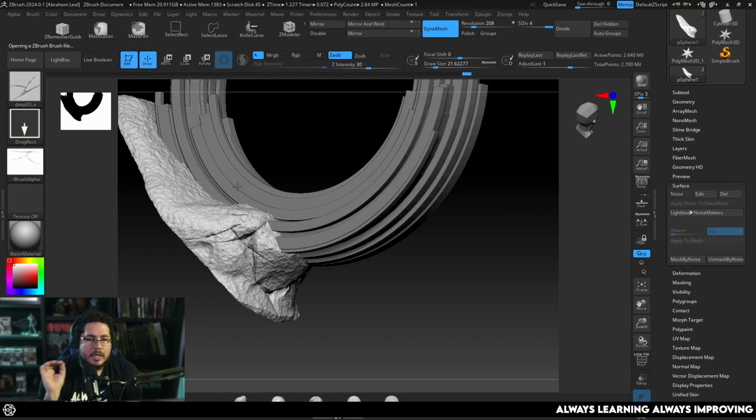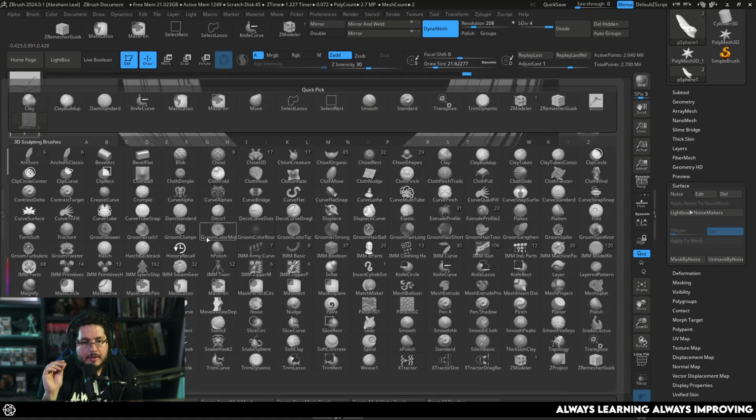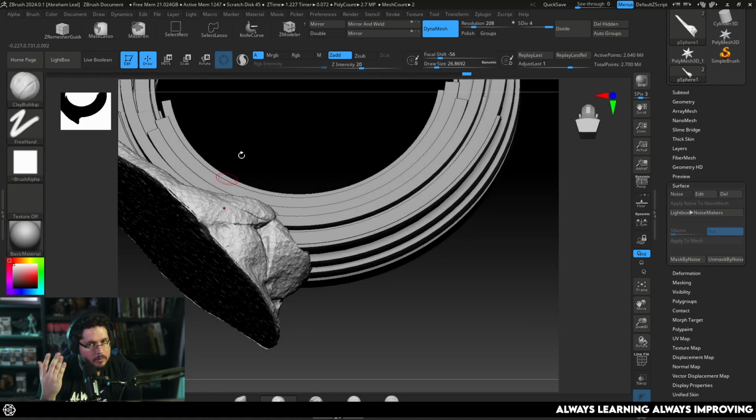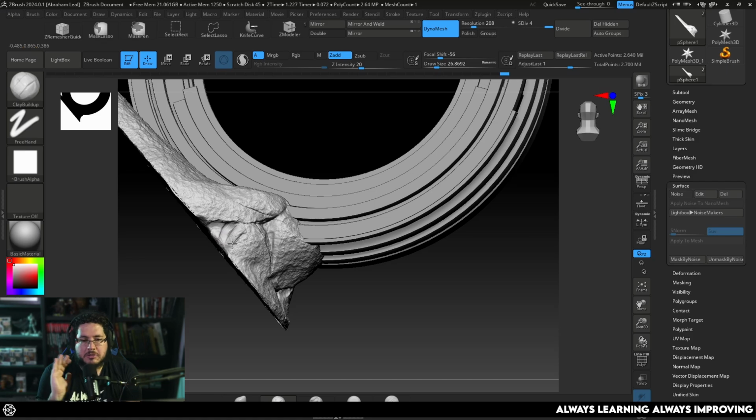3D print doesn't care about topology. The only thing it cares about is watertight meshes, so meaning there's no hole and there's no infinitely thin mesh, and non-manifold geometry. Angles you can triangulate, but when you have a face that's sharing two sides, that's when you can get some problems. So in this case, no need to do that.